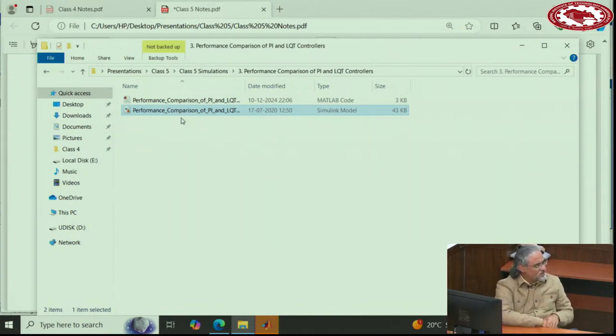So here I chose 1 millisecond for the low pass filter. Because we just calculated that if you have 1 millisecond, the transient time of the system, we chose the poles at about 1 millisecond, and we said that it cannot limit the current. So if you add that filter, it will help. You don't want to choose it 10 milliseconds, right? Or even a fraction of a millisecond. A fraction of a millisecond for current limiting is good, but it will have the problem of bringing the noise of the grid to the feedback loop. But if you mean delay in the feedback loop, no. Here, the delay of the low pass filter does not go to the feedback loop.